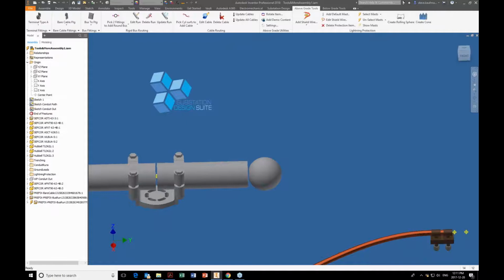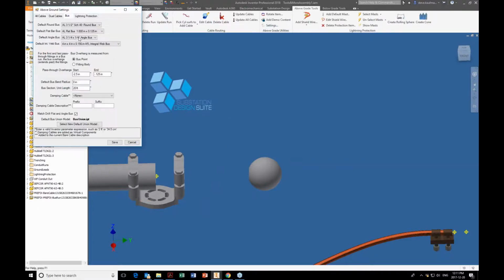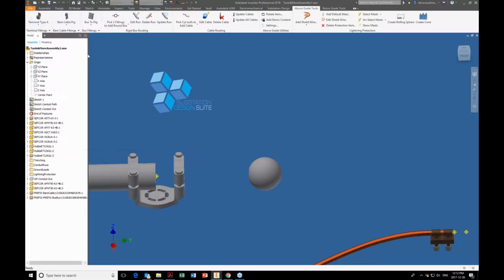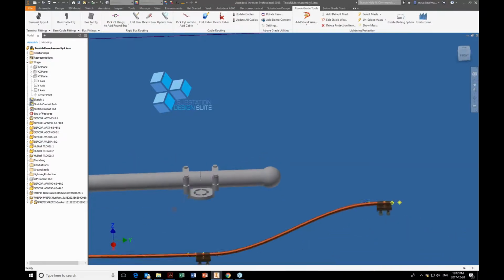Okay. So I can get that offset to the point where I want it connecting to the fitting. And I see I put the wrong numbers in, so let's get the right numbers in. I don't want to spend too much time on this. 0.1 and negative 0.1875. Pick fittings. All right. So we have our piece in here.